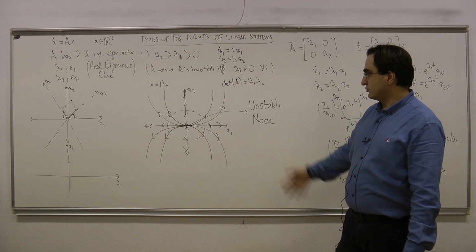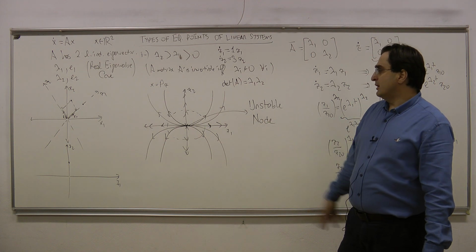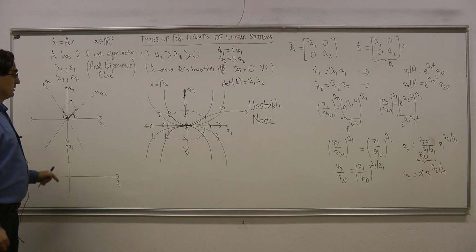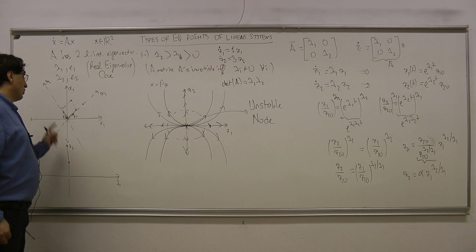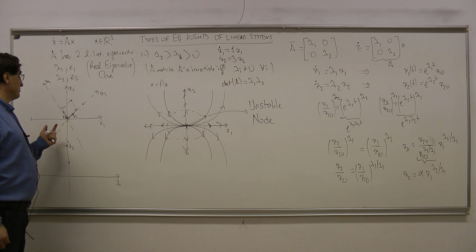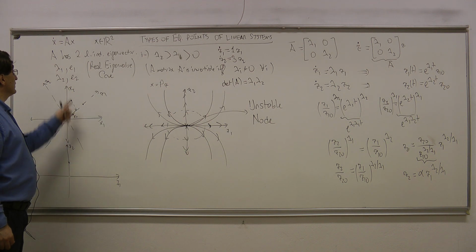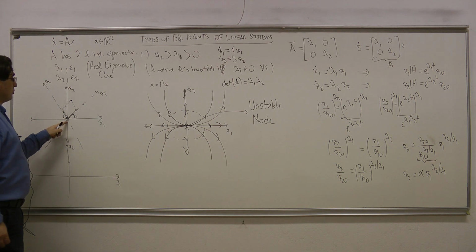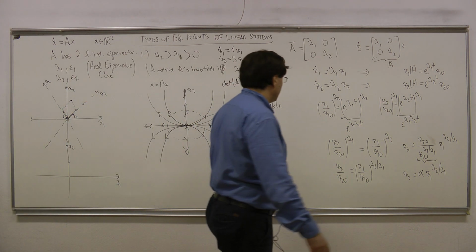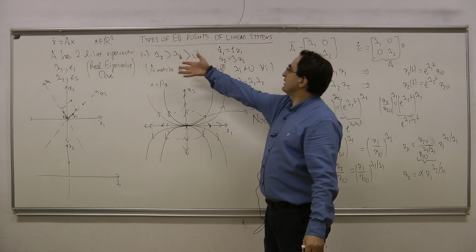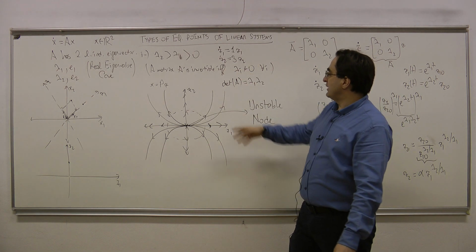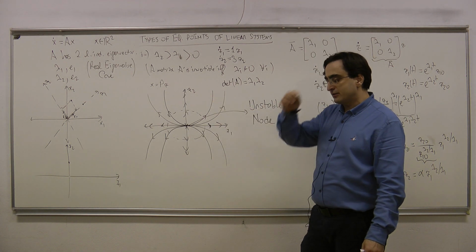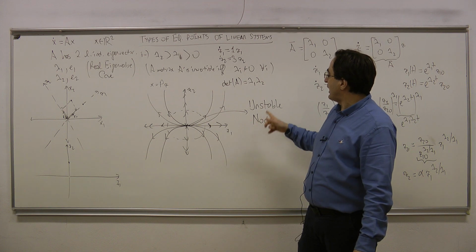That is a sentence that you can hear in control theory. Similarly, we're going to classify the original equilibrium point of the original system as an unstable node. Okay? So we are going to decide on the type of the equilibrium point by looking at the eigenvalues of the A matrix. If they are both real and positive, then that equilibrium point is going to be called an unstable node. If both of the eigenvalues were negative, then the directions of the motion would be changed here, but I might have similar trajectories. In that case, the equilibrium point would be called a stable node.